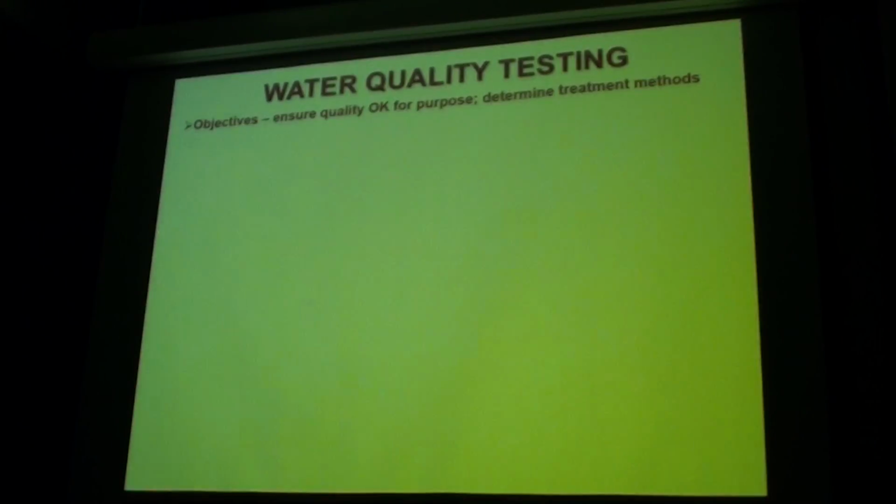Okay, testing water quality. We need to know if our water is going to be drinkable when we start taking it out permanently. Initially it might not be so. We've developed this well, so there's still stuff in it. There's still a bit of filter cake, there still might be material left in there from the drill and all sorts of bits and pieces. So after the first maybe day or so, you can take water out and collect it. Along the lines that I said earlier, it'll be in specialised bottles. The people at the labs will deliver you these sorts of bottles, especially to collect water in, with some different chemicals, all sorts of things.